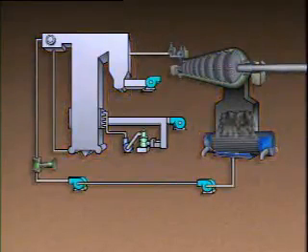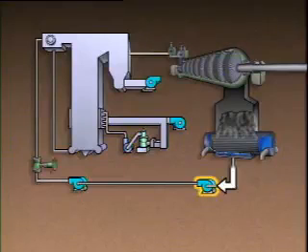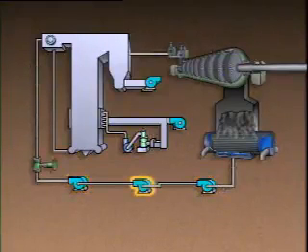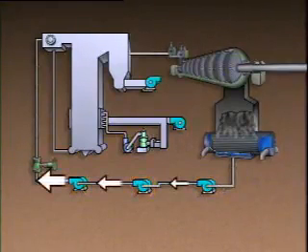This is done with a series of pumps in the condensate feed water system. One pump, called the condensate or hot well pump, removes water from the hot well. Next, the feed water pump pushes the water into the boiler. Some plants use a third pump, called a condensate booster pump, between these two. Each pump along the line adds pressure to the water.